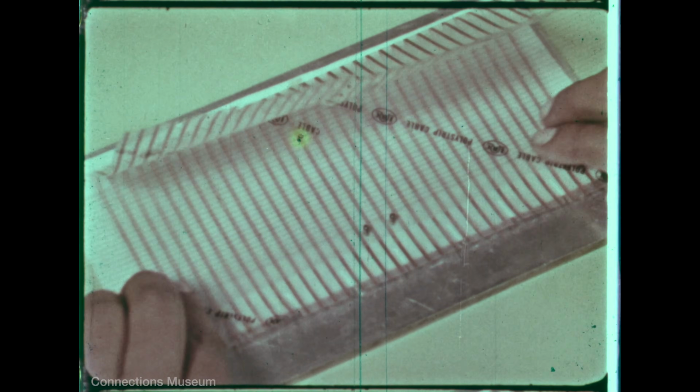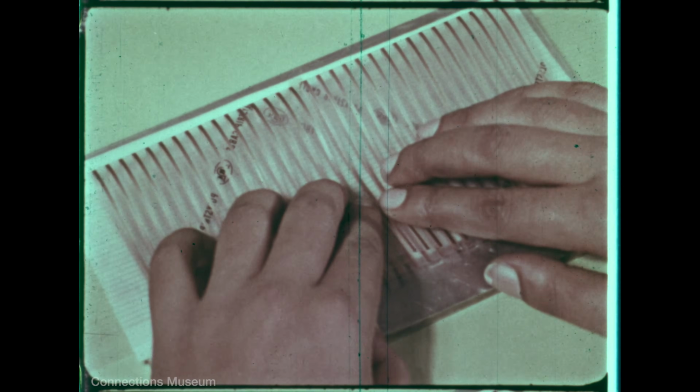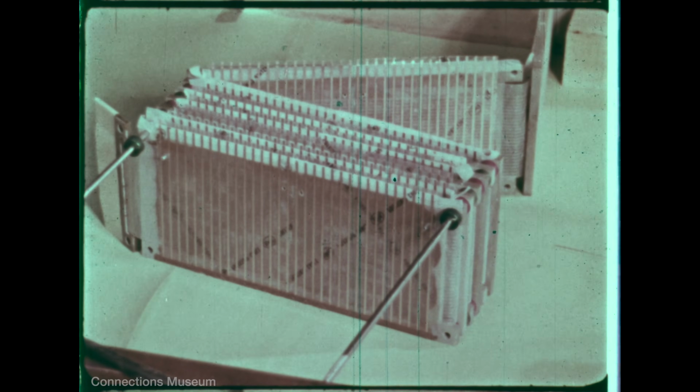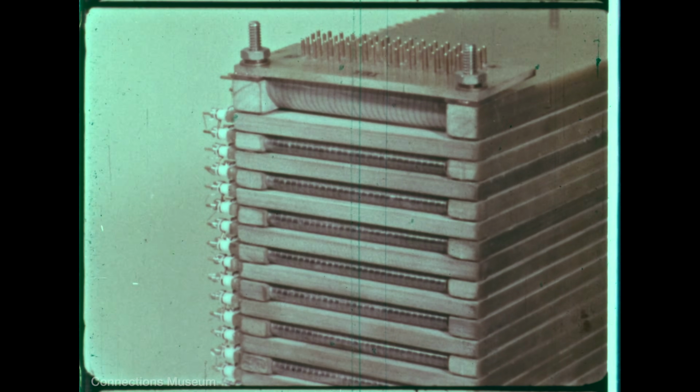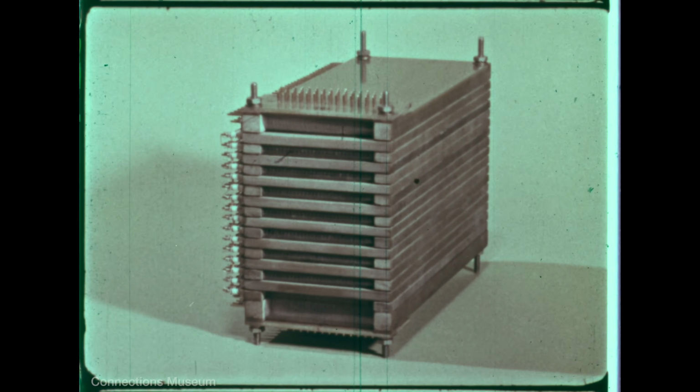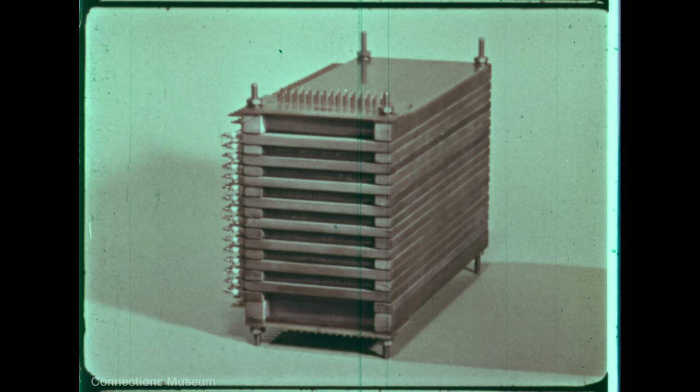For larger capacity, another type of twister memory has been developed. Instead of coils, the solenoids are copper bands, which are embedded in plastic and folded over the sheet of twister wires, forming a coordinate grid. Bits are stored at intersections as before. 16 similar grids are made along a continuous sheet of twister wires, which is then folded into a stack of planes. This 3-dimensional array can store about 15,000 bits with an access time of only about 5 millionths of a second.